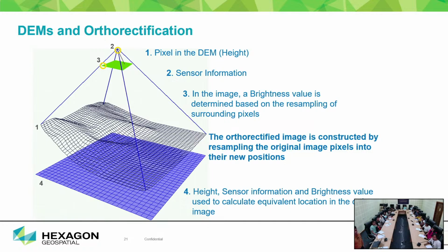Orthorectification means we have satellite data that looks like a flat surface, and we have DEM data, and now we have to generate a product using the information of the DEM data, that is the Z value, and the satellite imagery's value, that is the XY location and the DN value. So we can superimpose the DN value of the XY location over the Z value. That is the whole and sole concept of the orthorectification.